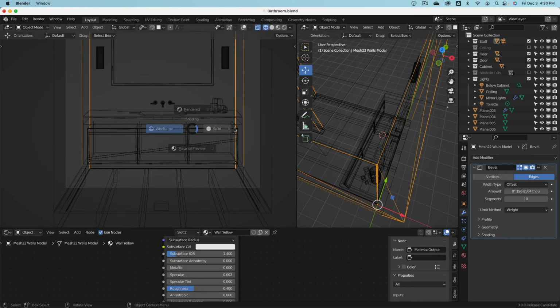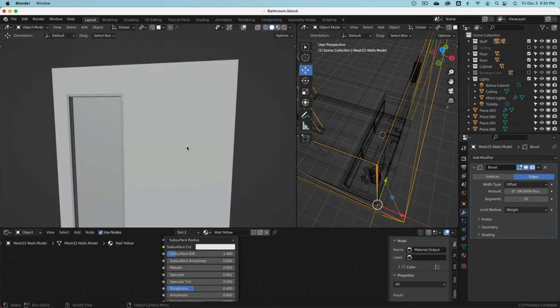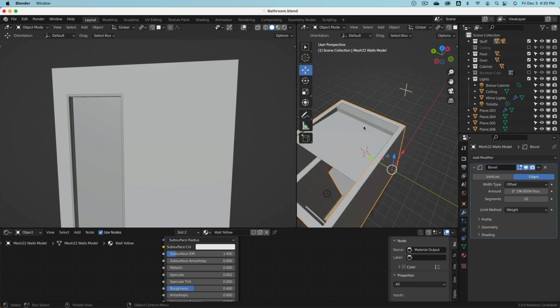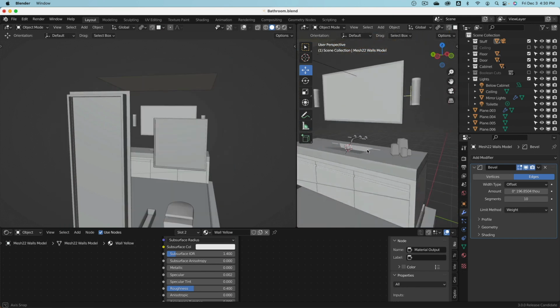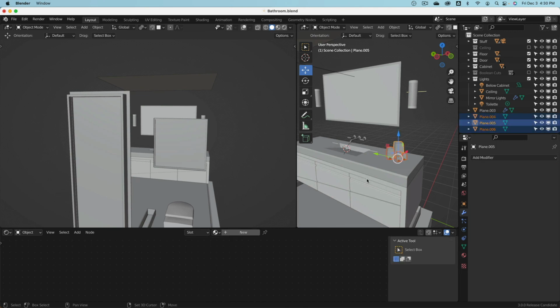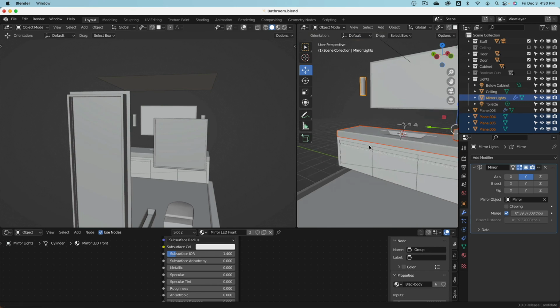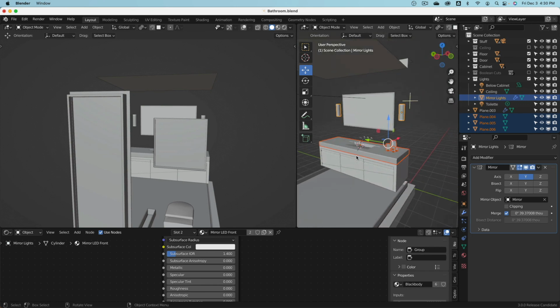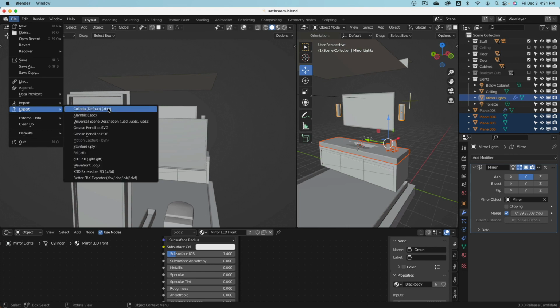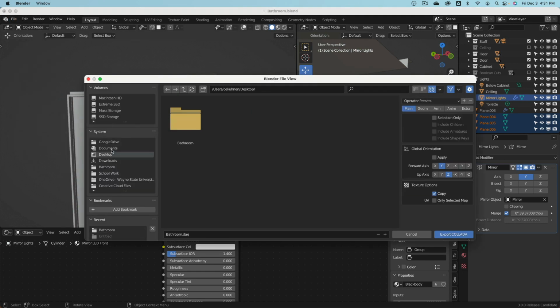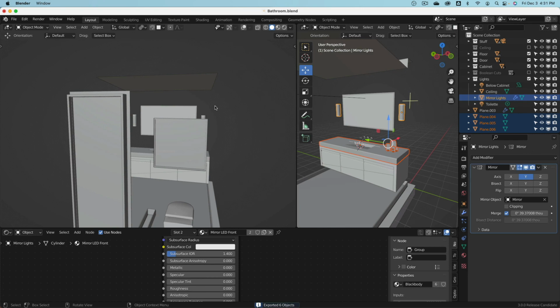And now, how do we get everything back? Oh, and this is pretty easy. So UI height, I select you. The cabinets I leave out, I could do, but for this exercise, I just leave it out. So these objects are selected, File, Export, then Collada, Desktop. There we are, very good. So we set selection only, geometry, and away you go.